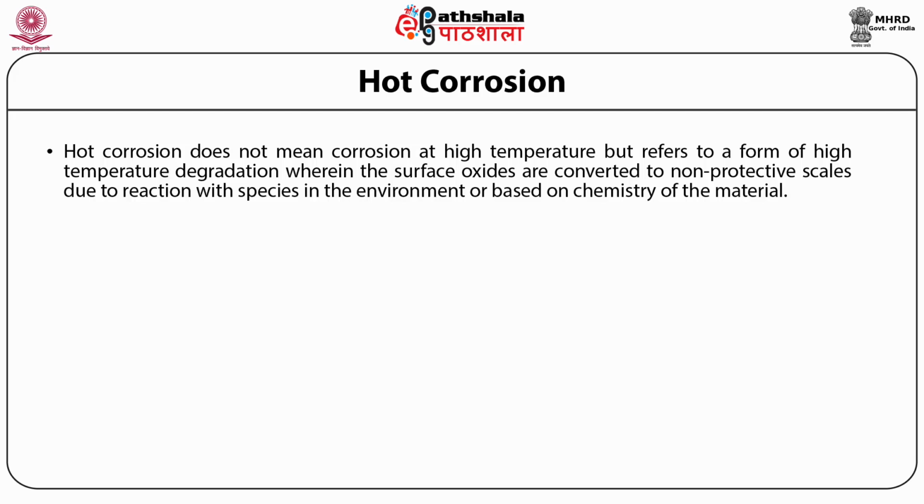Let us take a typical example. In the case of jet engines, air is injected and then compressed, mixed with the fuel and ignited. The gas produced is at a temperature between 700 and 1400 degrees Celsius. Part of the gas is used for providing thrust to the airframe and the rest for running a turbine that supplies power to the aircraft.